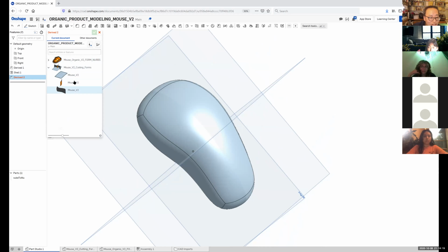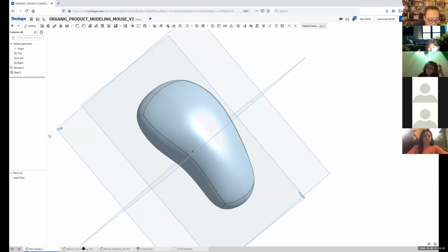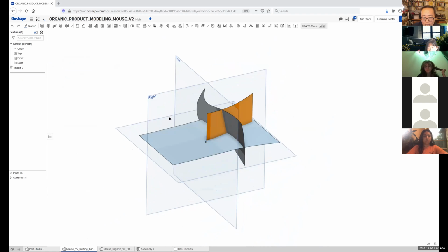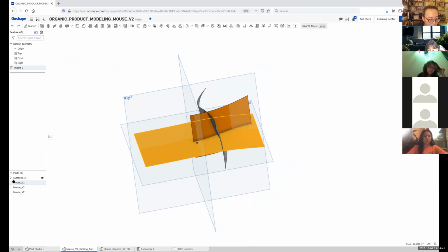So let's open this up, and here we have these. Fortunately, we have 3 different names, right? Now, notice how the name is shortened, right? Mouse V2, mouse V2. Well, what if these icon shapes are not really revealing what these are? How do you know? Well, let me go back to here. I recommend going into this file and examining and properly naming these under this list of surfaces here, okay? So that's advisable. In fact, I'm going to go into Maya and copy the name from Maya and then just paste it in here, because I don't want to invent new names, okay? So I just went into Maya, and I'm going to do rename and then just paste that. Yeah, see? Beautiful.